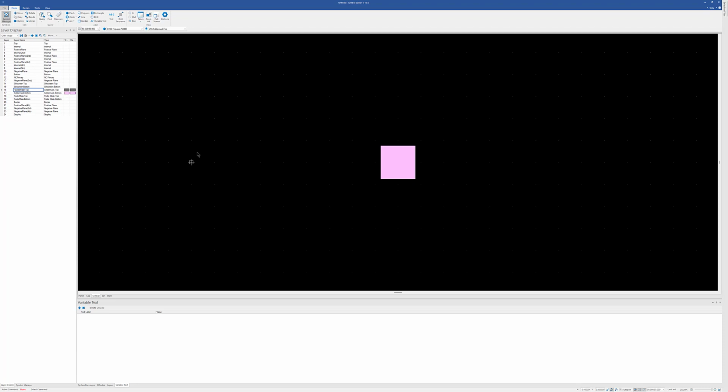Okay, so now we have a pad on our 2 outer layers with solder mask clearances. What do we want to populate with our coupon on our internal layers? Now, I've got a few options here. I can just say add it to internal, and whatever I put here will put it on all internal layers. Doesn't matter if they're plane layers or signal layers.